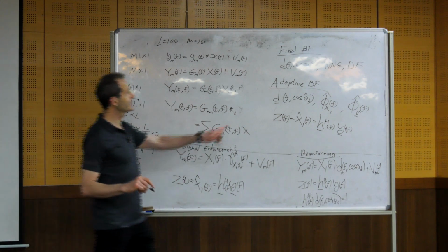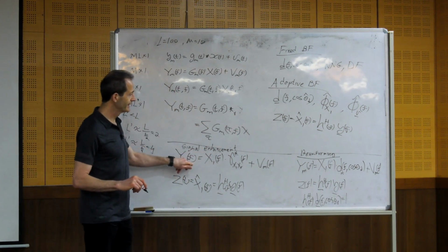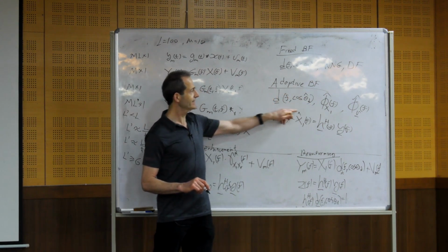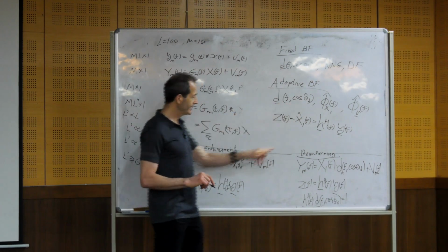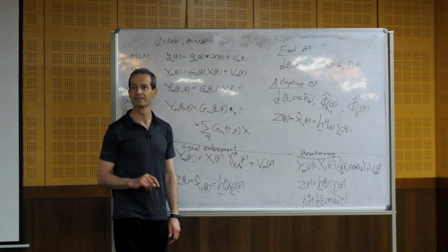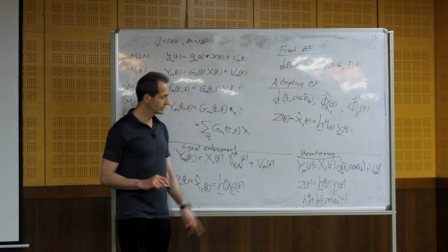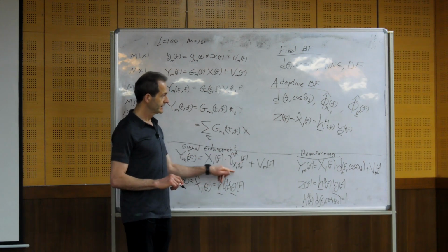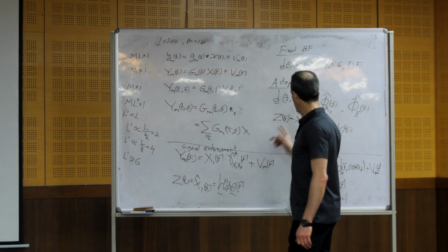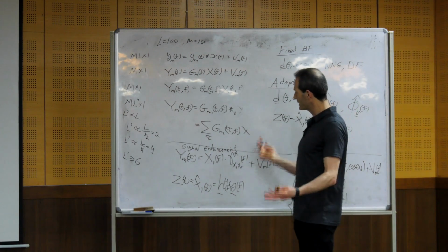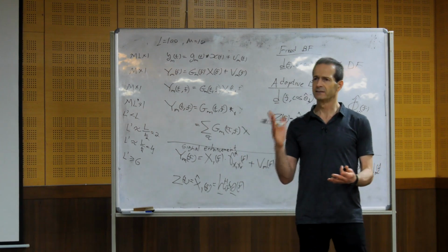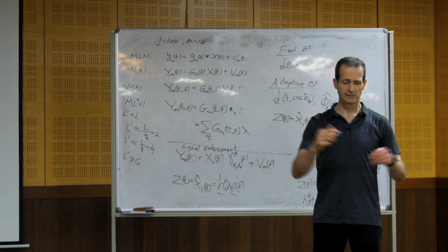So the difference between adaptive beamforming and signal enhancement is that here I assume a direction. You see, here I assume a certain direction. Here I try to find the relative transfer function. This is the difference. So here I need the correlation matrix phi x, or actually I need the steering vector, which takes into account not only the direct path, but all the reflections.